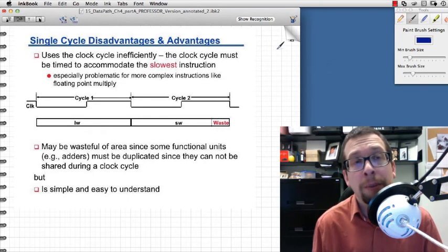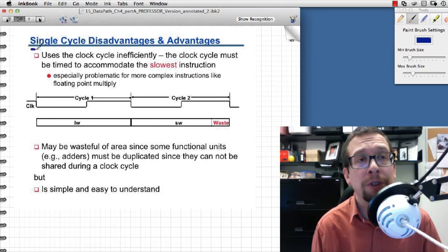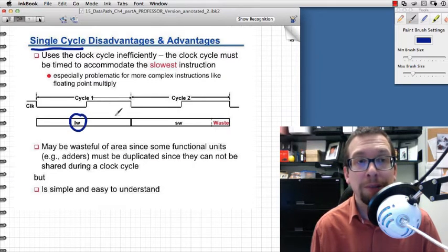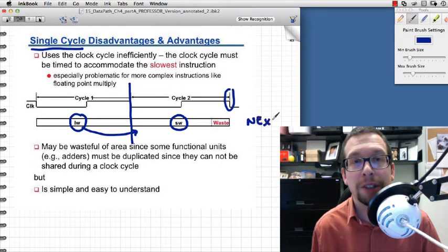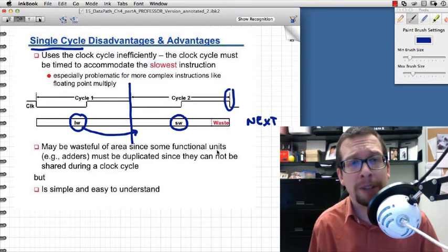And there are two main types of architectures that we need to talk about at this point. The first is what's referred to as a single cycle instruction architecture. And that refers to the chips that basically do one instruction, finish it, and then when the clock changes, it starts executing the next instruction. And when the next instruction is finished at the end of a particular clock cycle, the next instruction after that executes. So it's relatively straightforward. One happens after the other.